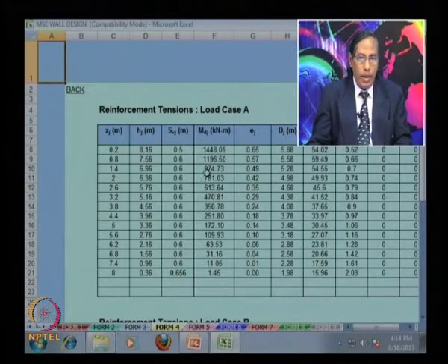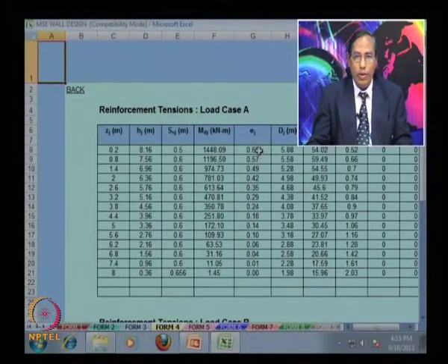Here MDj, what is the driving moment, you can calculate for various depth. So you will obtain this defined value, and you can see the driving moment value is gradually decreasing. Then it is Ej, that is the eccentricity of the resultant vertical load at the jth level in the wall. So you can calculate what is the eccentricity for varying depth.